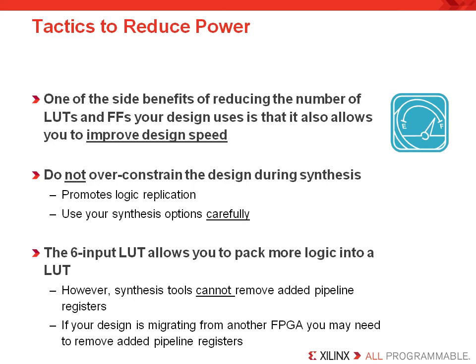You also need to be aware that over-constraining your design during synthesis encourages the synthesis tool to replicate logic automatically. Designers also need to take special care when they are migrating an existing design to a newer product because the newer products have a more efficient 6-input LUT, and the older devices had a 4-input LUT. Now this is important because many FPGA designers have used pipelining to optimize the speed of a data path. If an older design was pipelined, it probably has several unnecessary flip-flops that will actually limit the performance and increase the power necessary if it's targeted to a newer device. These designs should be re-pipelined appropriately for the architecture.